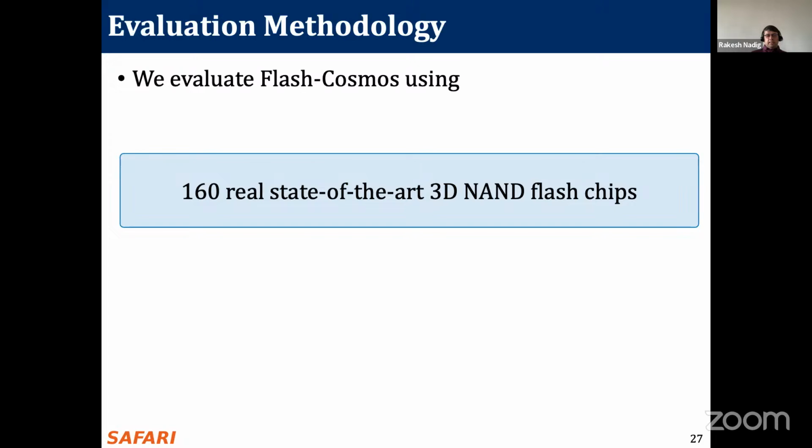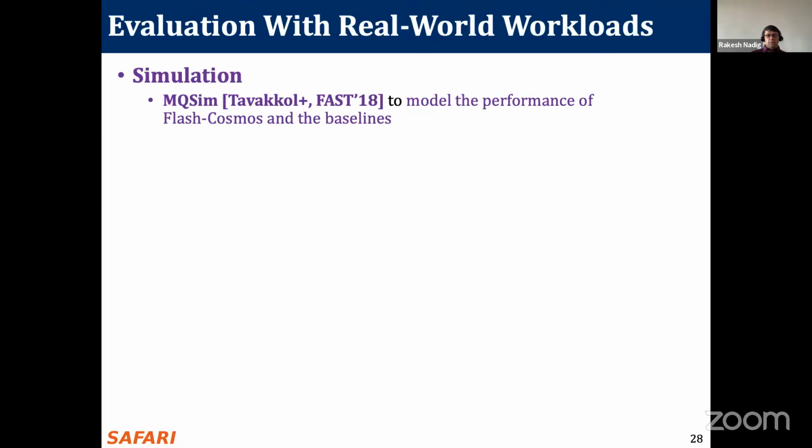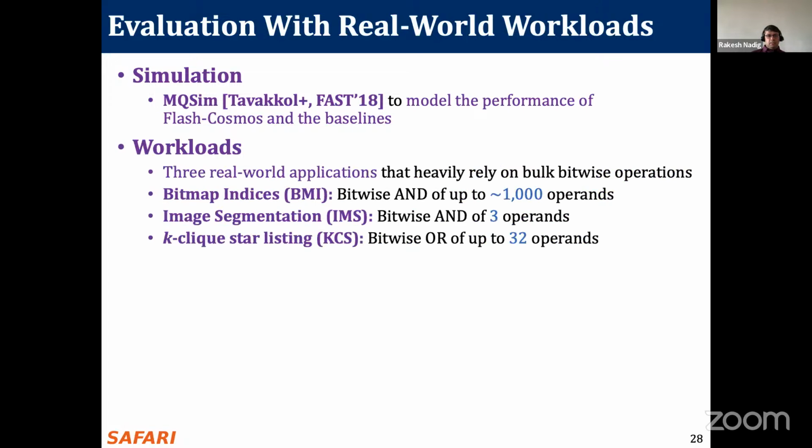Now, this is about the real device characterization to check the feasibility, performance, and reliability of Flash Cosmos. To test the performance and energy efficiency of Flash Cosmos at a system level, we use 3 real-world applications that perform bulk bitwise operations. And to do this, we use a state-of-the-art simulator called MQSim to model the performance of Flash Cosmos and the baselines.